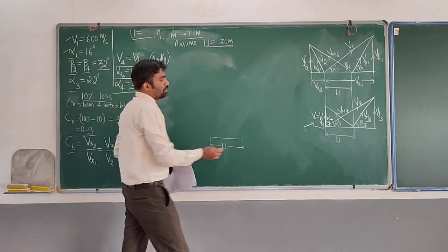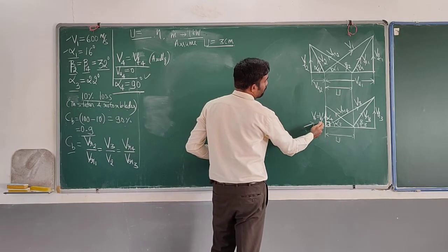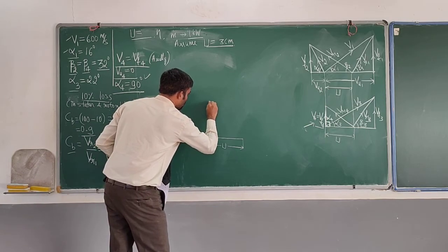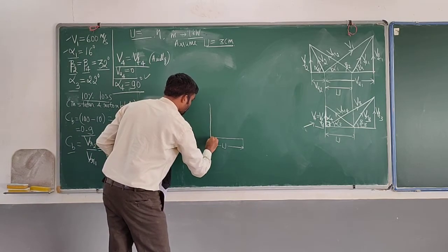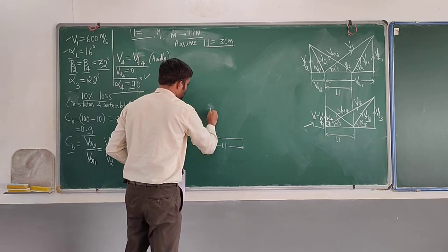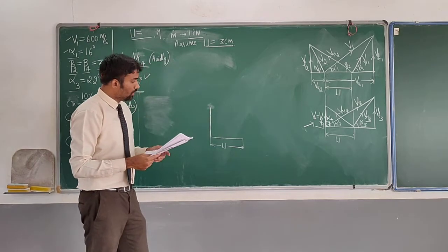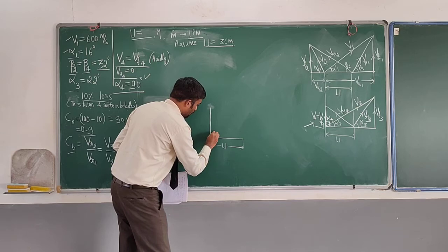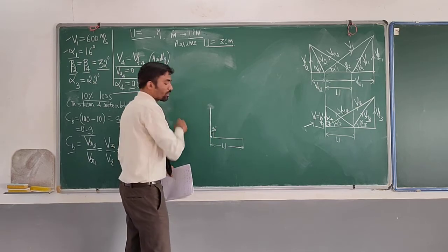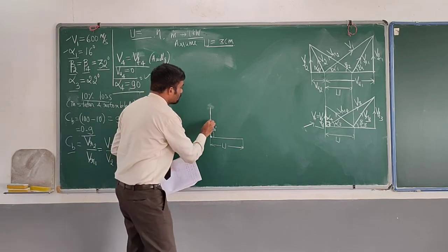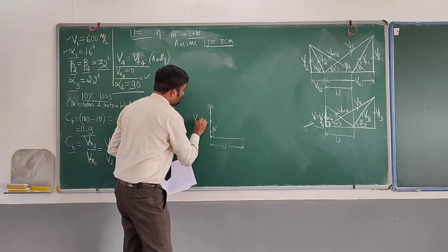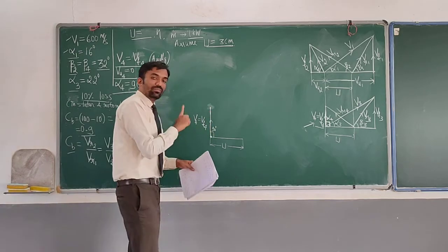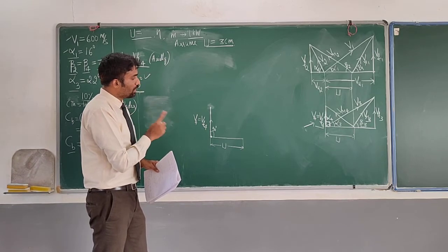So what is the next step? We know that V4 is equal to VF4 and it is just a vertical line. So I draw a vertical line of some random length, from one point of the u. Here I can mark the angle alpha 4 as 90 degree. If this is V4, it is also known that it is equal to VF4. So V4 and VR4 meet at a particular point.